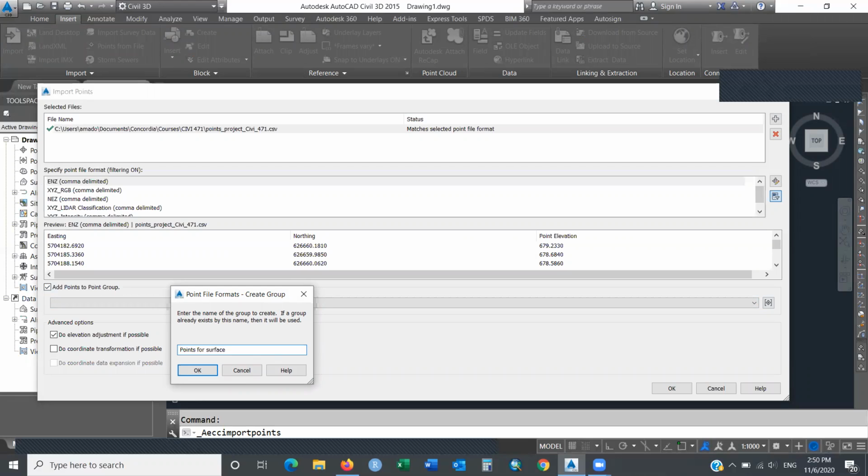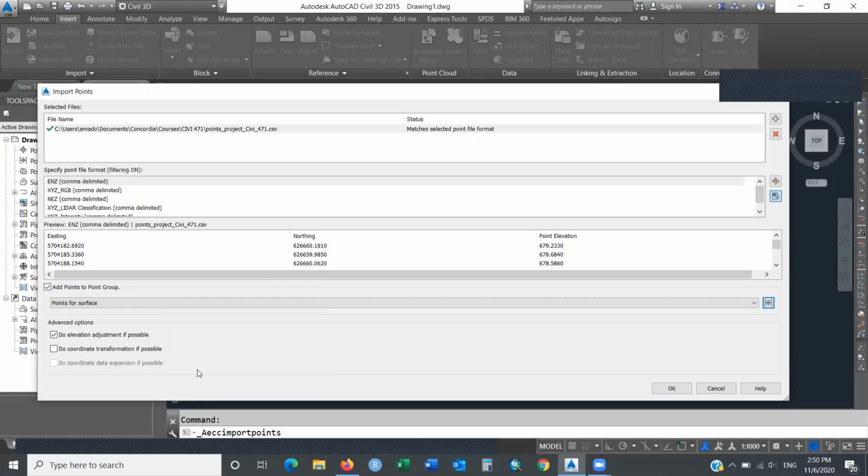So you guys have done this before. But please do not use the one we have been working with, because we have to go all the way back to the definition of horizontal and vertical alignments before we can insert the intersection. You cannot put an intersection if you already created a corridor. The corridor is not going to let you do it. So basically we have to start from 0 for this lab today.